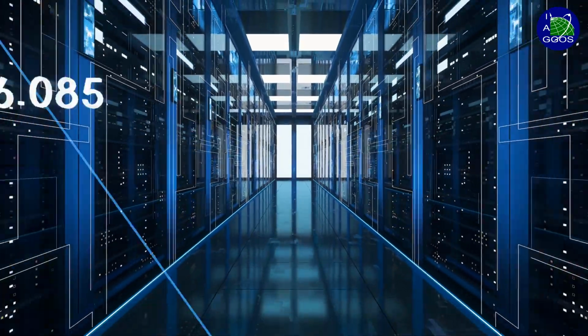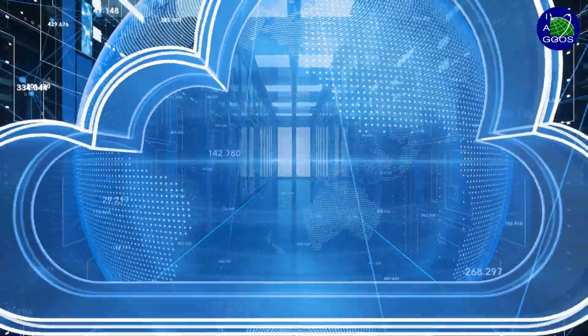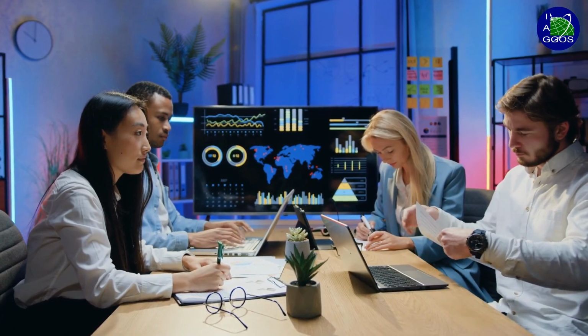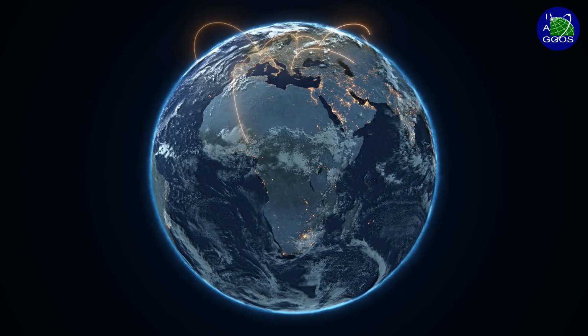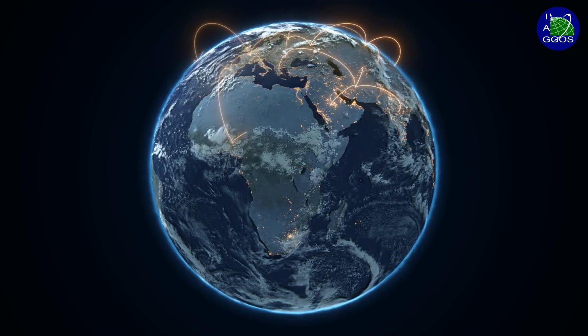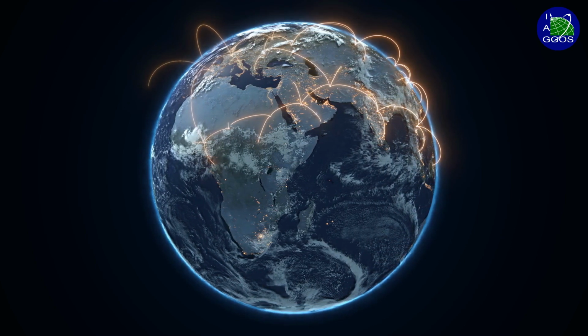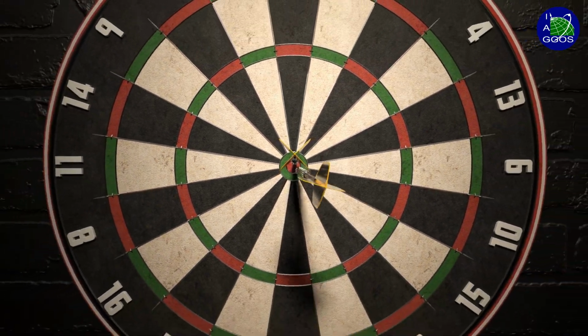Data collected at an observatory is then sent to data centers, which, in turn, provide access to this data for analysis and combination. The ITRF is materialized by computing the time-dependent coordinates of more than 1,800 geodetic Earth observation instruments. This task is done with millimeter precision over many years.